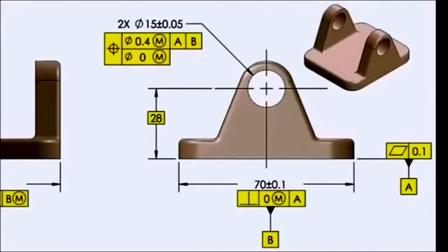The May 2012 tip explained the meaning of a 3-segment composite position tolerance where the primary datum feature was repeated in the second segment. Location of the pattern is controlled by the top segment of a composite tolerance. If datum feature references are repeated in lower segments, they are there to refine the orientation of the pattern of features relative to the datums established by the referenced datum features. Here's a gauge that helps illustrate this concept.